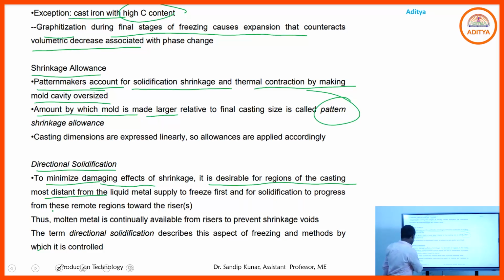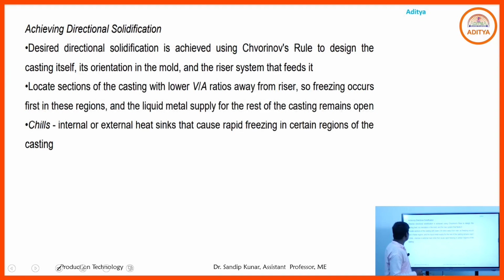Then molten metal is continually available from the risers to prevent shrinkage voids. The term directional solidification describes the aspect of freezing and the methods by which it is controlled. Solidification first starts in the mold cavity, then it comes to the riser. It does not take freezing first to the riser. First the solidification starts in the mold cavity.